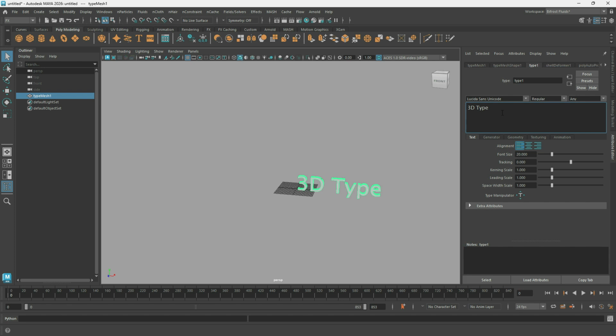The most important bit initially is this big box under the Text tab. Let's get rid of the default. How about Beginner Type Maya Tutorial? See how it updates live in the viewport? Pretty neat. To demonstrate the next settings better, let's move Tutorial down to the next line. We can also pin this Attribute Editor tab, so it stays visible even if we select something else.